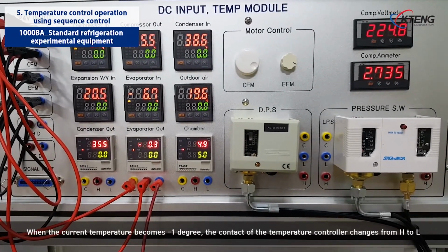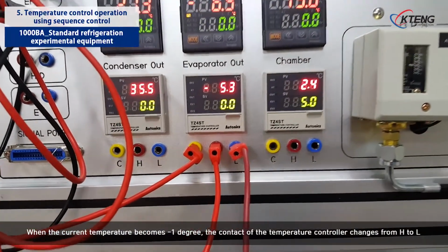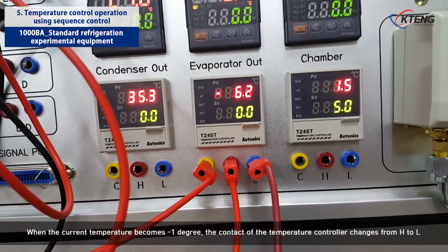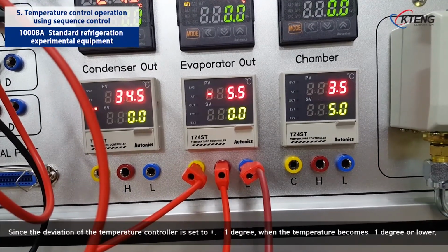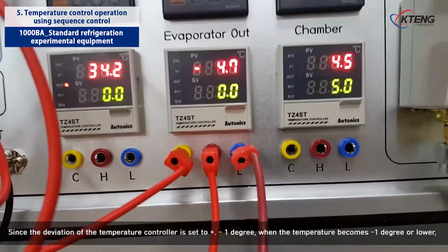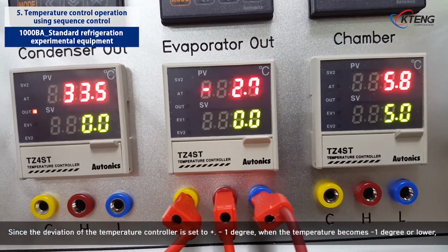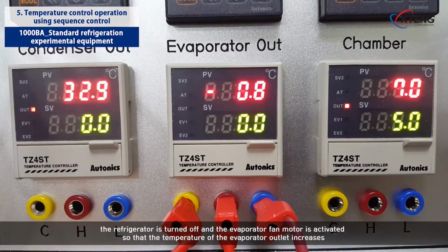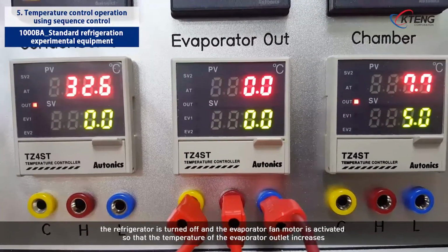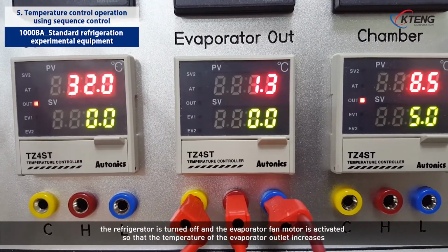When the current temperature becomes -1 degrees, the contact of the temperature controller changes from H to L. Since the deviation of the temperature controller is set to plus-minus 1 degree, when the temperature becomes -1 degree or lower, the refrigerator is turned off and the evaporator fan motor is activated so that the temperature of the evaporator outlet increases.